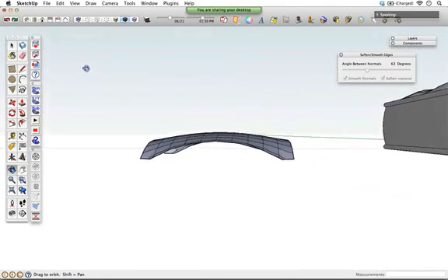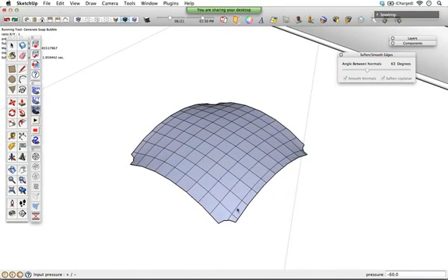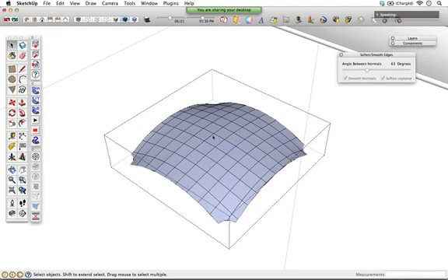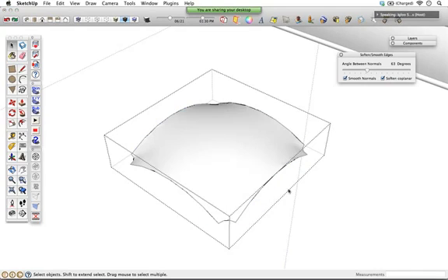And that's what gives us that little bit of a billow in addition to the seams that we have drawn there. So then we can go with the select tool, triple click that, soften smooth, reverse faces.